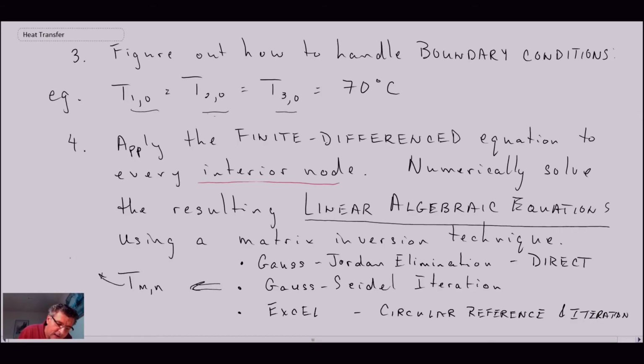And that essentially is then giving us T(x,y), where x and y are at each of the discrete node locations that we established in the grid generation step at the beginning. So if you want finer resolution, make delta x and delta y smaller and you'll get finer resolution in your solution. But of course there would be more points and it would take a little bit longer in terms of the numerical analysis.